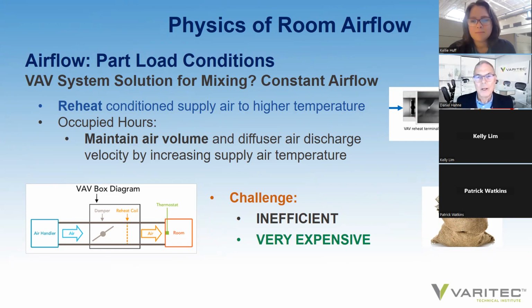So the only way to condition the space is to have reheat to the VAV boxes that hold that air at constant flow rates in order to maintain a space temperature set point.